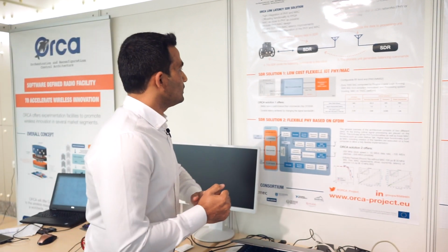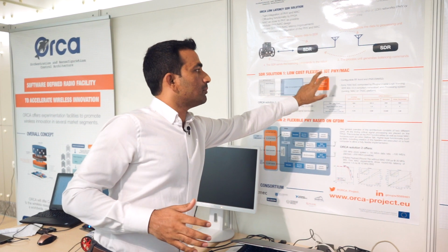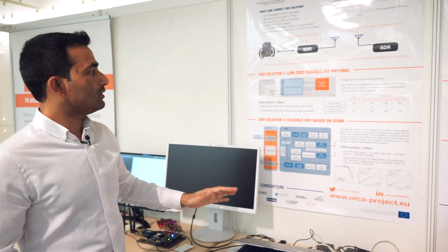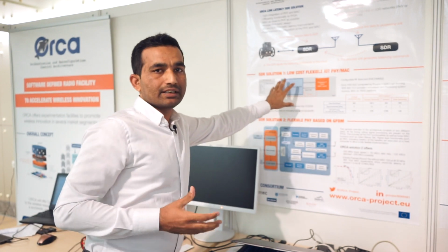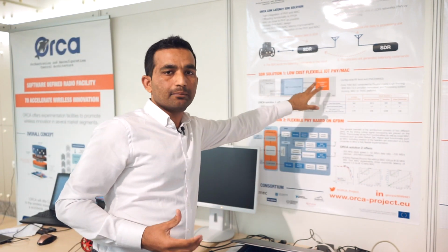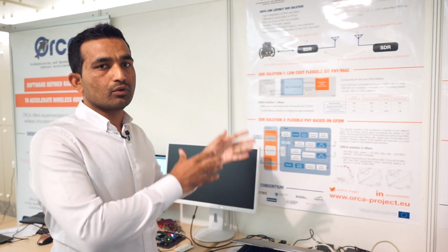So how do we achieve low latency? That is really a good question. We have made many improvements from the MAC layer to our front end. For example, we have used a pipelining architecture in the FPGA that helps to achieve low latency. Another modification is in the MAC layer on the processor. Normally a processor needs to read and write data from memory. We have a DDR-RAM memory.